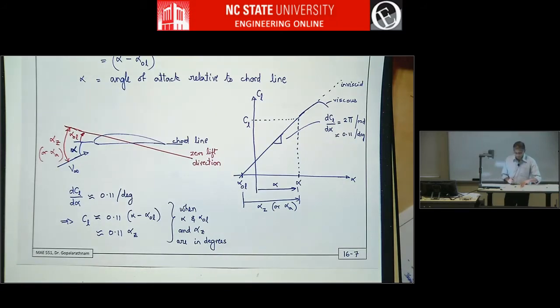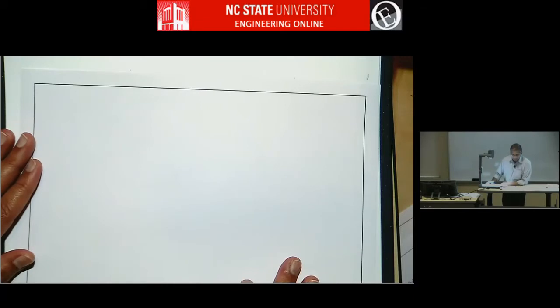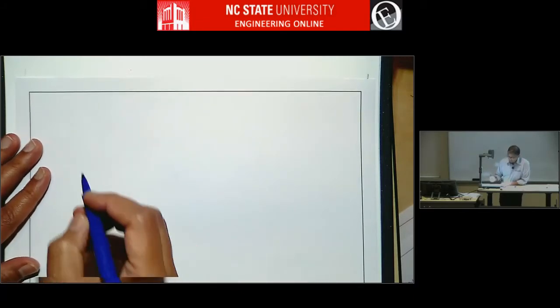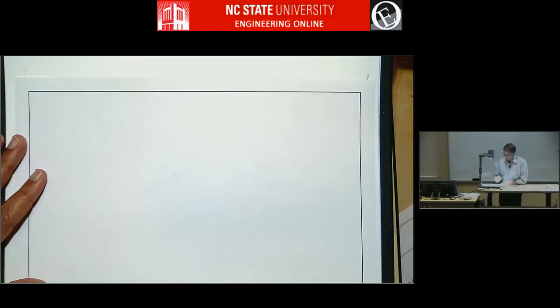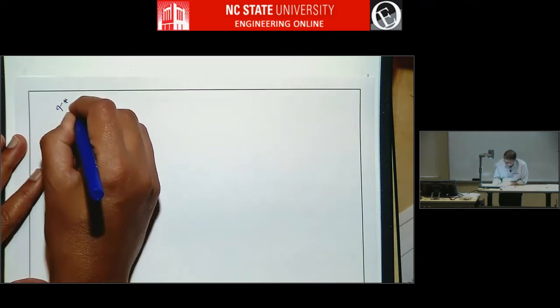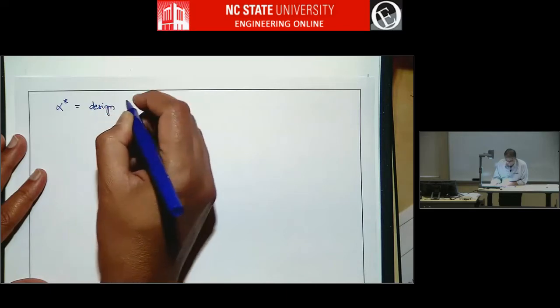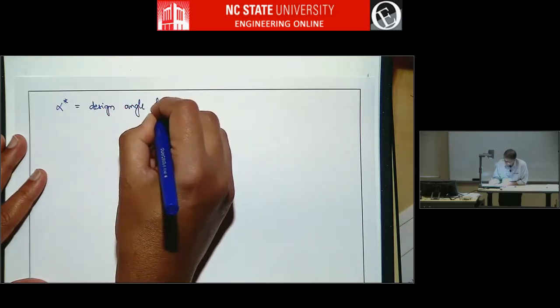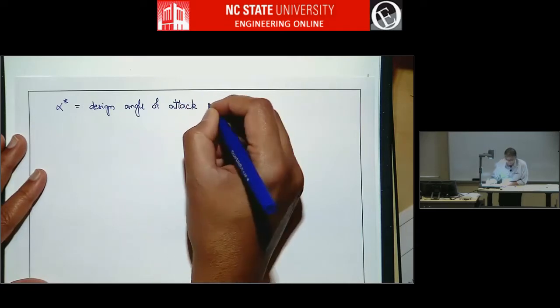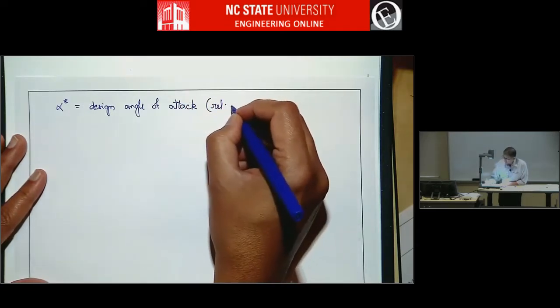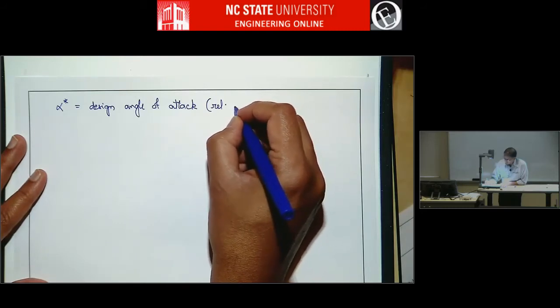So that means now all this connects to alpha star. So by specifying alpha star for a segment, you're essentially prescribing the design lift coefficient at which the segment has zero velocity gradient. So alpha star, that's the reason why this is defined relative to alpha 0 lift.